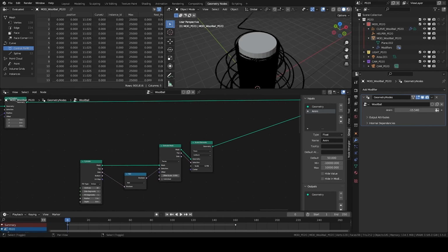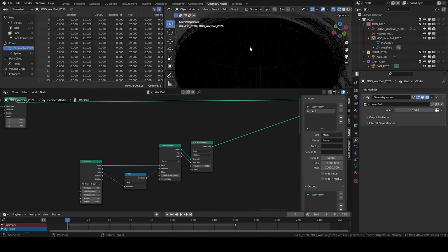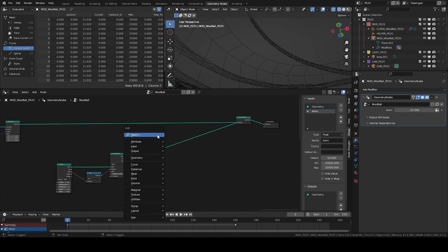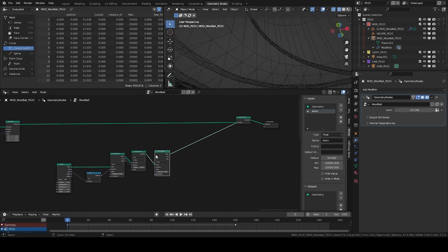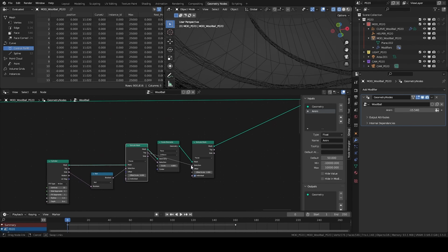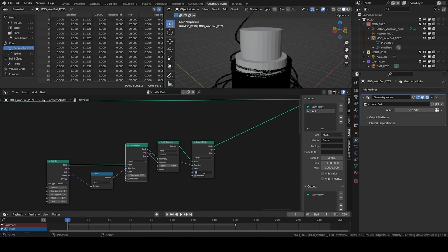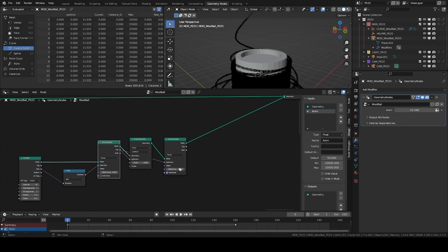I'm reducing my mesh a little bit. You can only see it in wireframe. If I go over here, we're going to see that I'm extruding inside. I put 0.8. Extrude mesh again, in which I reconnect the extruded face from the top. But this time, not outwards, but inwards. So a little bit less, maybe 0.2 or 0.3 will be enough.